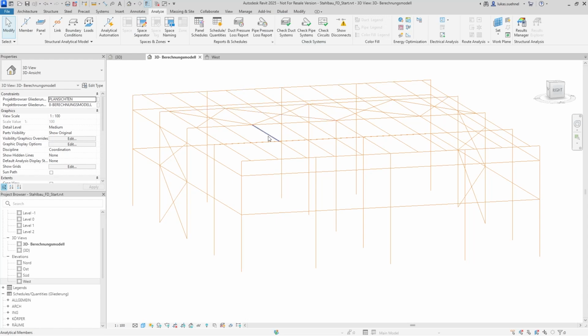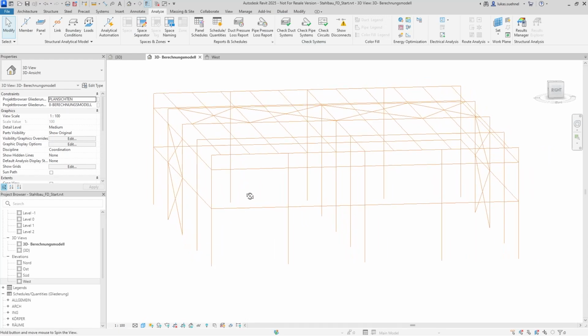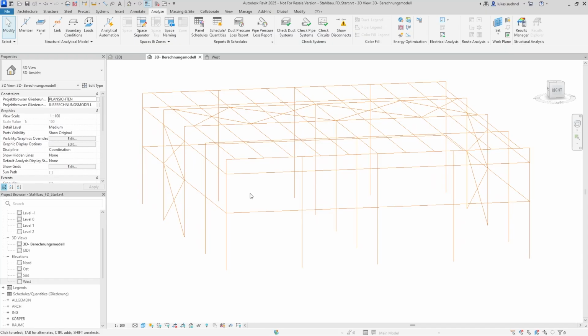And you can even fill these load cases with point, line, and area loads. So Revit has a basic set of analytical objects to optimize the analytical model. It is up to your decision how you want to work. If you want to have Revit as the main center BIM model and you feed all the other departments from Revit, or if it is just meant to be a simple data exchange, you want to support the structural engineer a bit, so you create the analytical model and you send it to him. So it is up to you how much information you want to pack into that model.